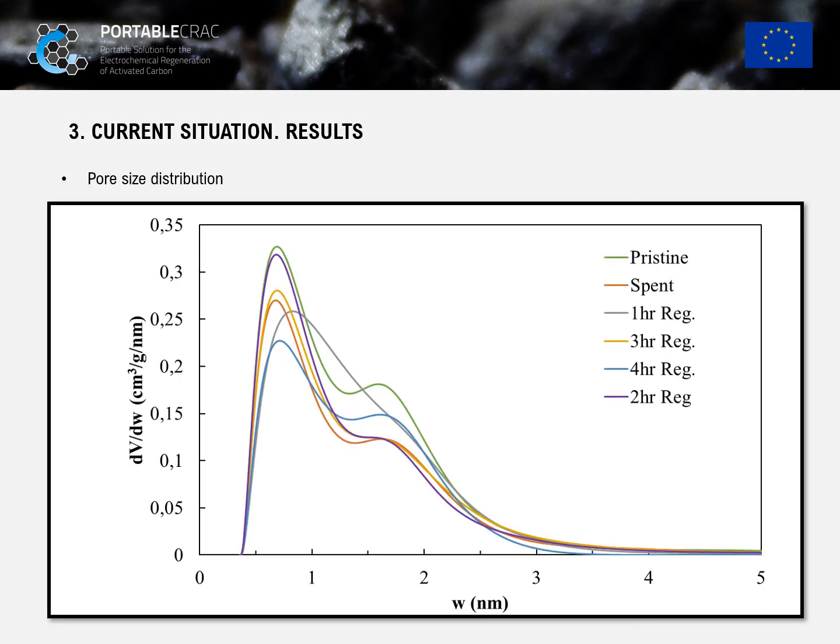This chart shows the recovered volume at different pore sizes during the regeneration. The sample taken after 2 hours of treatment shows a significant volume of pores below 1 nanometer, closer to the pristine sample. However, the sample taken after 1 hour of treatment is still the one with the overall highest volume of pores.